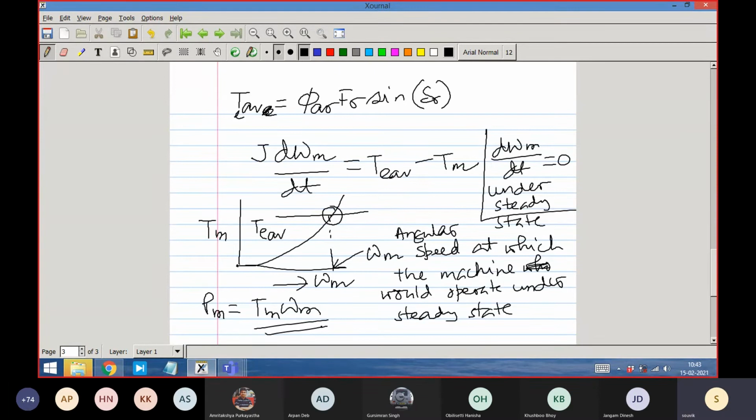And the coil, giving a coil. So what are you dictating there? So if I apply a voltage across a coil in terms of resistance, I am dictating the current? No, you are not dictating current. Current will be dictated by the load, by the torque that is produced, by the speed at which it is reached.